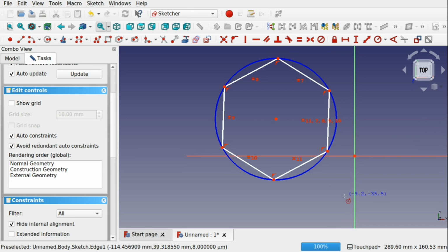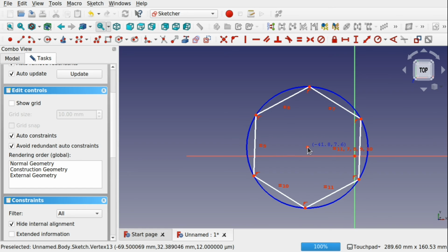If you're doing animation and you've got your center point in the wrong place and you haven't created the right center point here and you're trying to do your animations, you can create another object in here and create it as a composite object, and that center point will be that last object you placed in position. You can rotate around that. It is best practice to constrain your sketches down, but at the end of the day, it's your world. If you don't want to do that, you don't have to. If you're working with speed and you just want something quick, it's totally up to you.